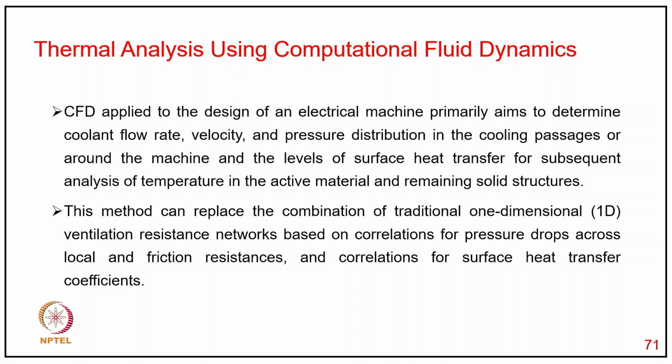So you can see a steady state finite element analysis of temperature rise in a slot with rectangular copper conductors. And now thermal analysis using computational fluid dynamics. CFD applied to the design of electrical machines primarily aims to determine the cooling flow rate, velocity and pressure distribution in the cooling passes or around the machine, and the level of surface heat transfer for subsequent analysis of temperature in the active material and remaining solid structure.